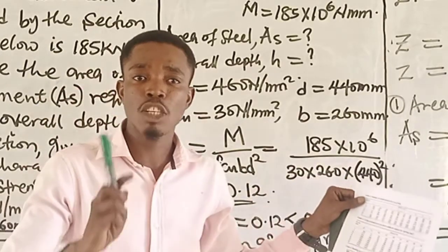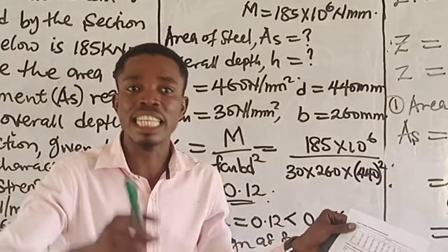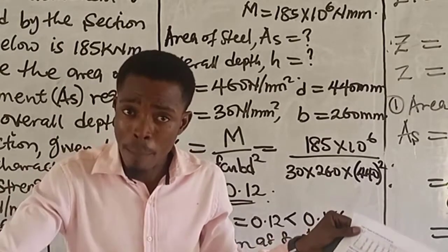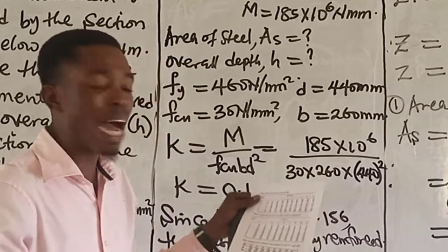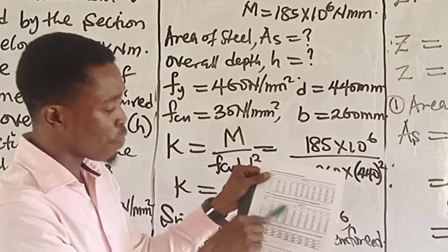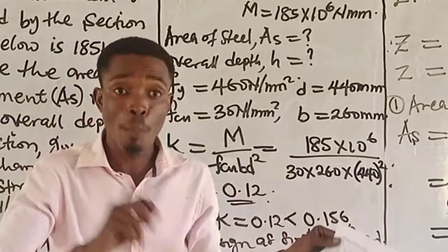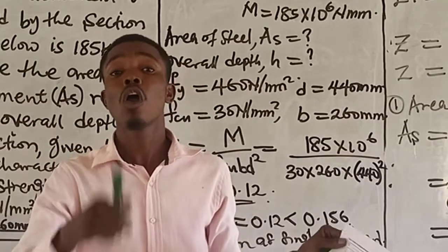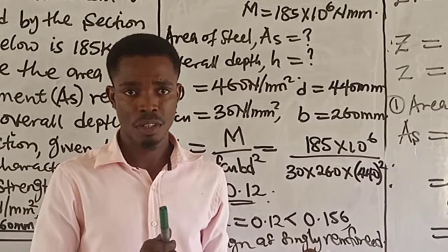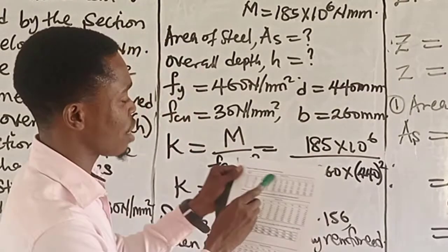When you are designing a structure, the ones that are in groups are either beam, column or foundation. For slab, they are area per meter width, and that is table 4 here. So anytime you are looking for group bars, we are actually looking at beams, columns, or foundations. If this is understood, now we will go to that section.